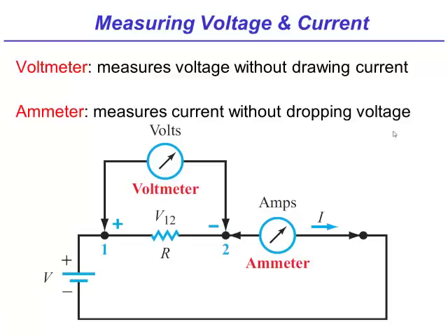So in this ammeter you've got shown here, current that would normally flow around the circuit from, say, node 2 and around this back to the negative terminal of the battery is going to flow through there anyway, but the ammeter won't cause any additional voltage difference. That's correct, because remember, the current goes through my circuit, and then now I've inserted that ammeter in there. The current goes through the ammeter and comes all the way around, and because the ammeter doesn't perturb the circuit, as far as the circuit is concerned, the ammeter is basically not there. So if I didn't have the ammeter here, I would have had this node here connected to that one. It would just have been a wire. Correct. Got it. Okay, that makes sense to me.